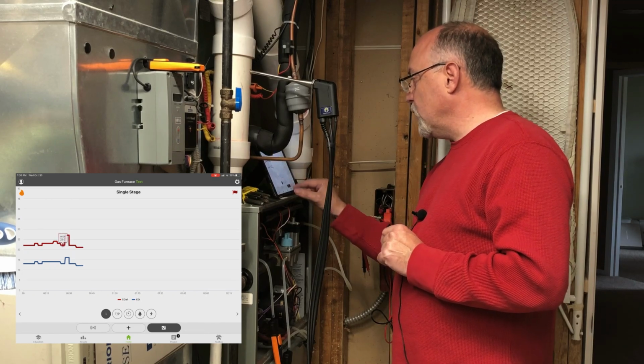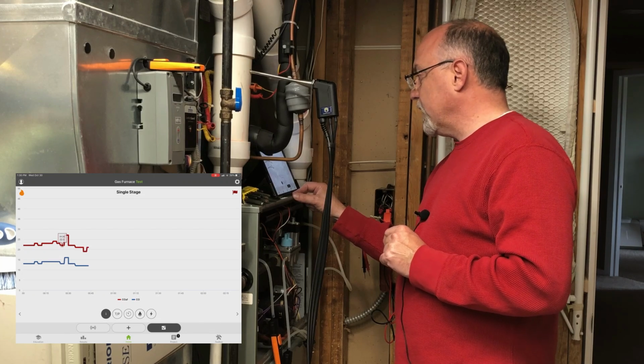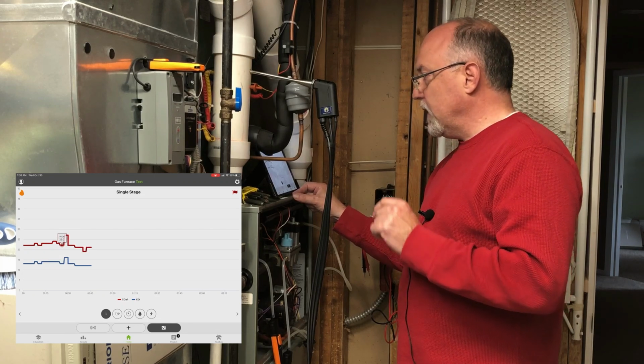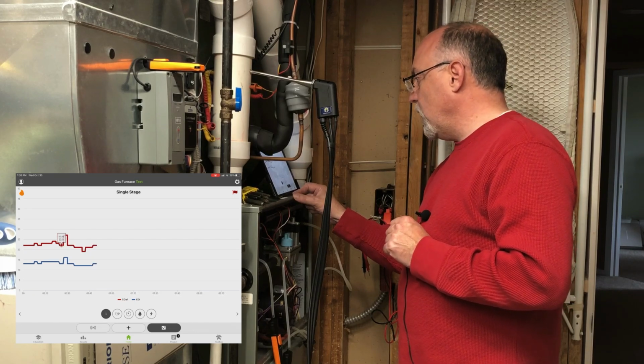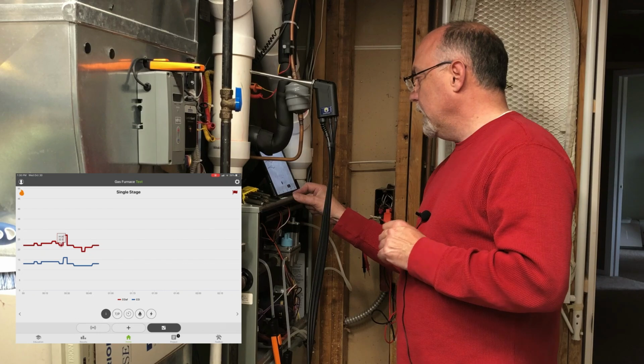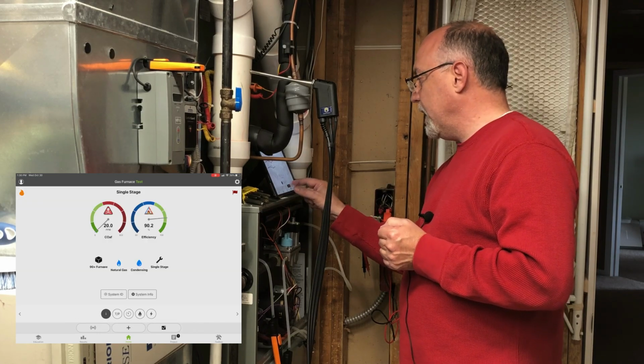So these small fluctuations like this in the CO air free are just indicative of the combustion. The graphing shows that at a lot more granular level than you might expect it to. But for all intents and purposes, this thing is stable. It's just small changes in the analyzer we're picking up in there, and that's okay.